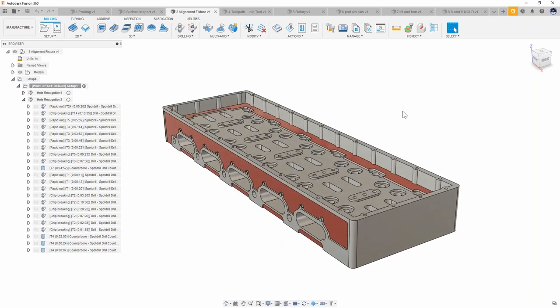And even if you have a part with a few simple holes, even when we're doing one hole that's a spot drill, a tap, and then maybe there's a chamfer or counterbore or something on that, this can be a very valid strategy, because even for that one single hole, it'll make all 4 of those operations. And obviously, if we have multiple holes, you can see we're making 4 operations for each size hole. That can be very time consuming, and this really automates that process and kind of takes it into the computer's hands here.